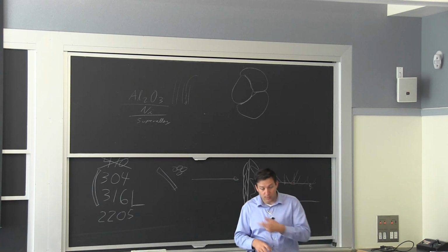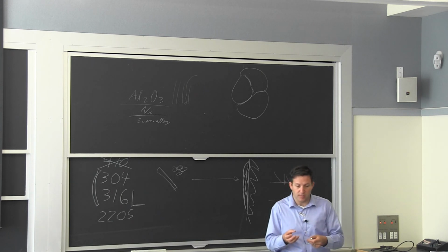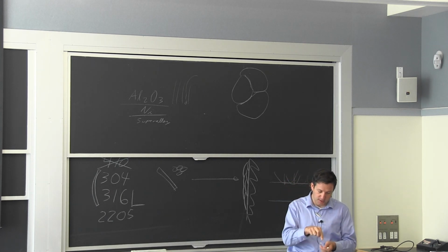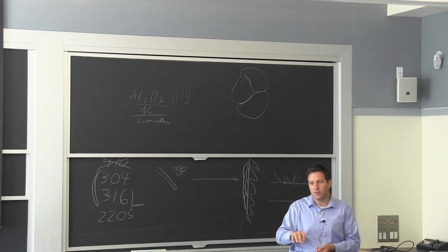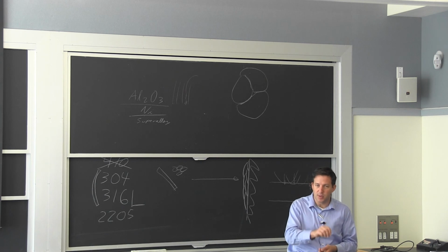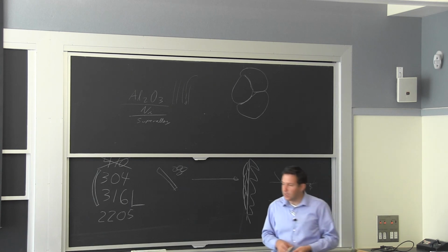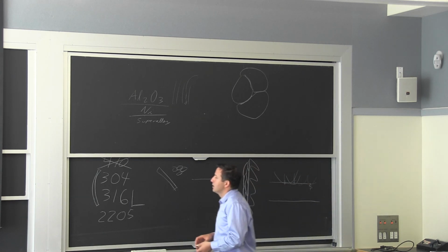And from what we've learned today with the laser sintering, it's very, very similar, except the laser will really stay at a point for a certain amount of time and then move on. So instead of being continuous like in welding, it's really spot by spot. And then you wait long enough so it cools off, and then you do the next one. In welding, you can do the same. You can do multiple passes.